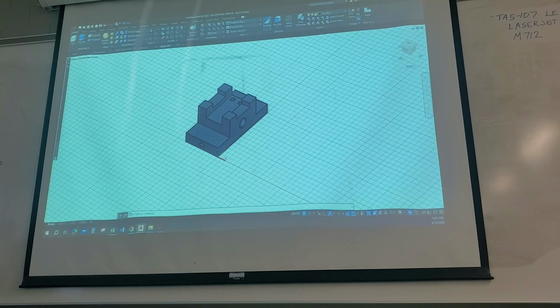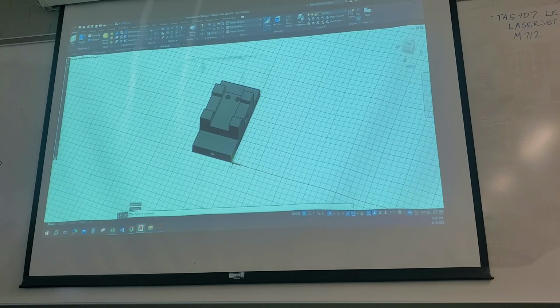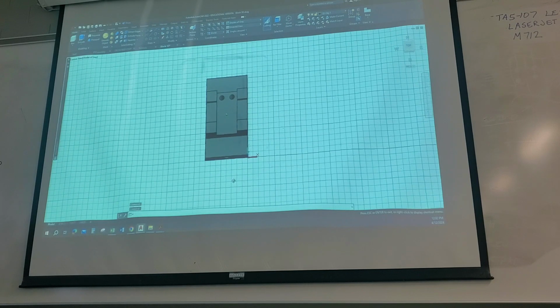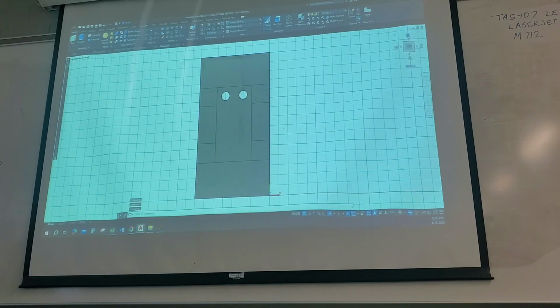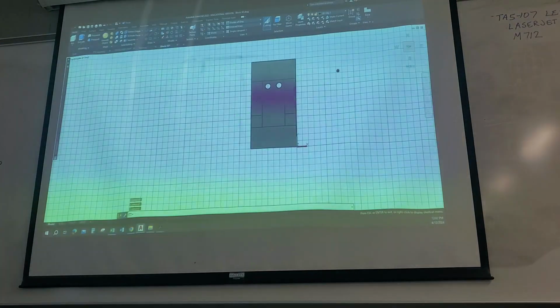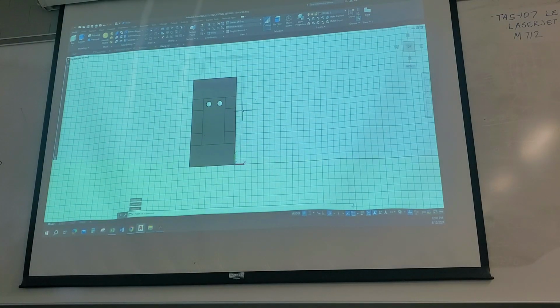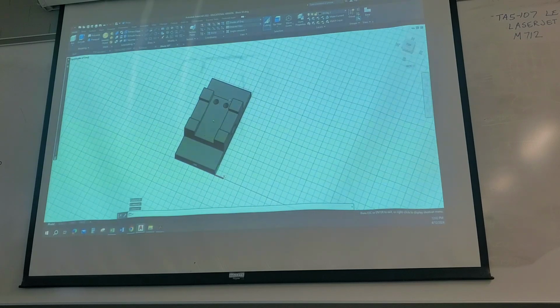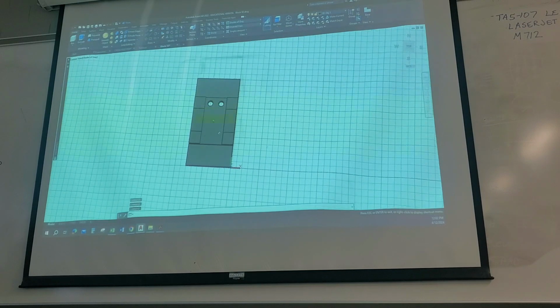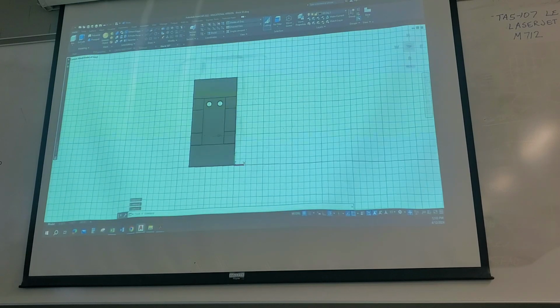So on this particular object right here, I've drawn it based on the information that I was given. Not just the dimensional information, but also 0-0. So on this one, we had 0-0-0 on the bottom corner right down here of that block. We had it positioned in that direction, which was our Y direction up, which is also, if you look up here on the view cube, AutoCAD also understands that to be your north direction. So we've got this object that we've drawn in 3D. The next thing we need to do is take it into a drawing for a presentation or a fabrication type drawing.